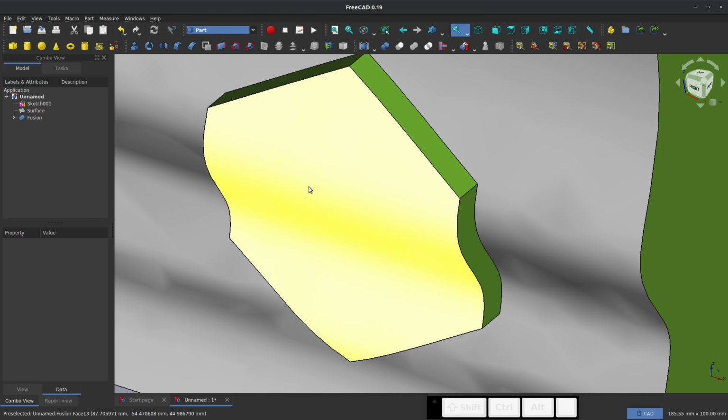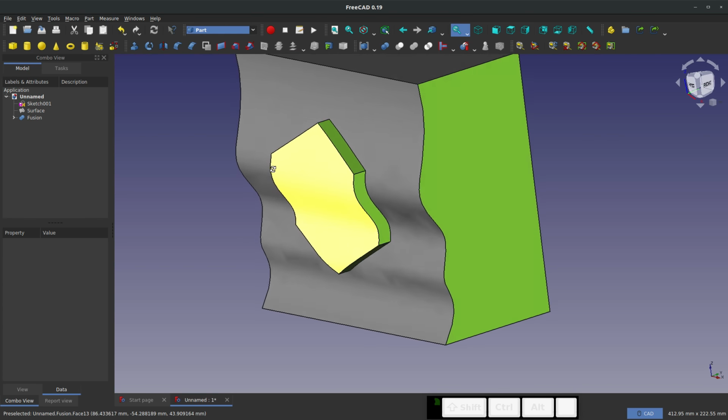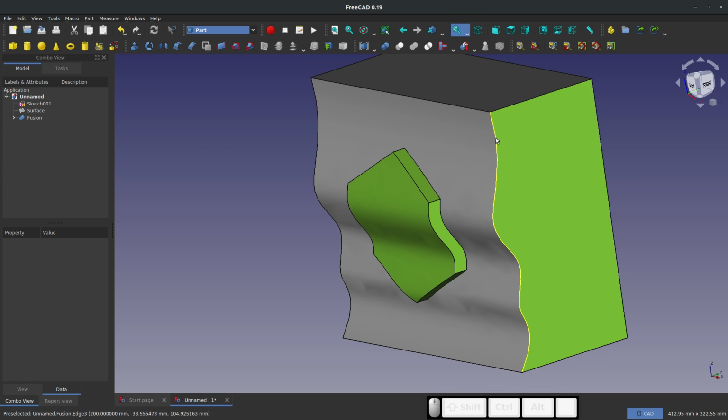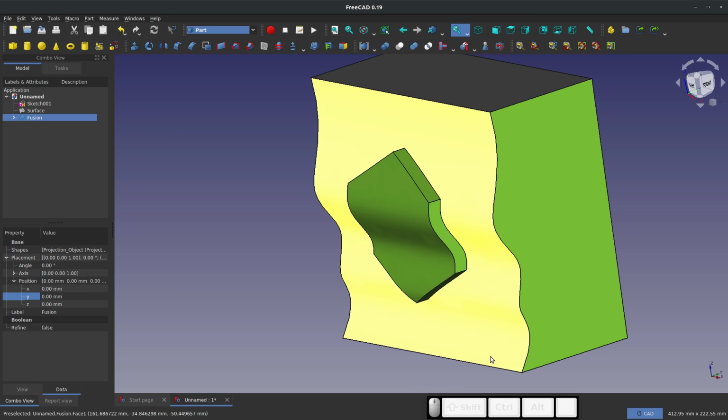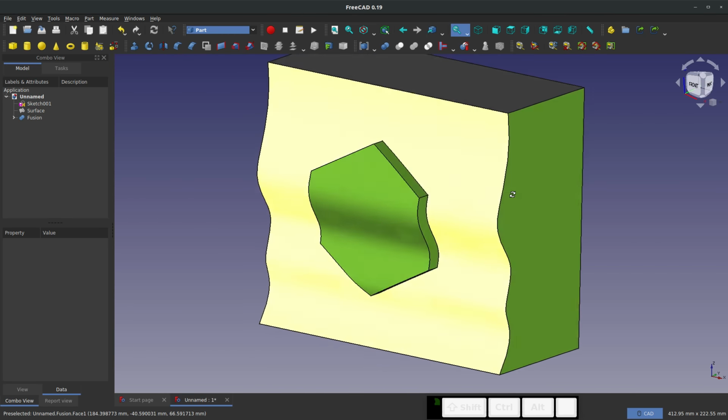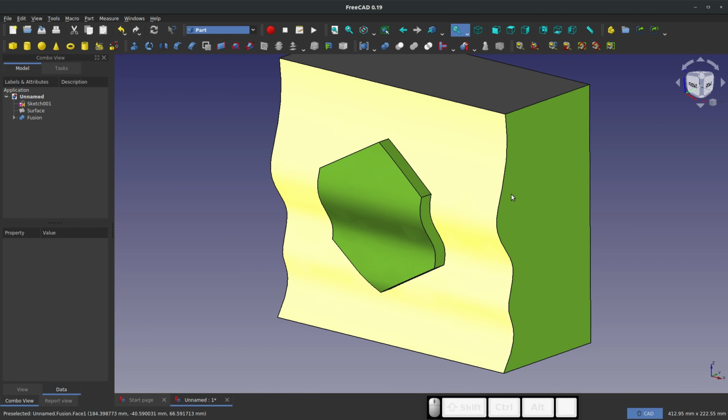So that's a very useful way of being able to project off of crazy NURBS-like surfaces. If I haven't mentioned already, the very, very overly simplified definition of a NURB surface is a surface that cannot be flattened. So this one can be flattened, so it's not technically a NURBS surface, but any surface like the top of the mouse surface, that one can't be flattened without distorting it. So it would be considered a NURB surface. That's a very simple, maybe overly simple definition of NURBS. It stands for non-uniform rational B-spline.